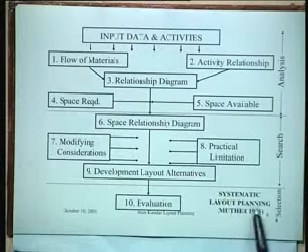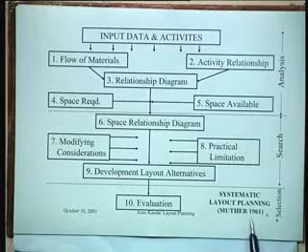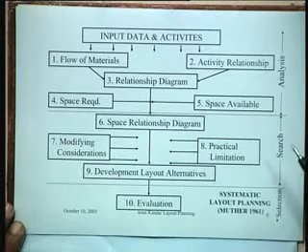Let us now look at the process of designing a process layout. Normally when you talk about layout planning, we are generally talking only about process layouts, because in a product layout, the layout is generally fixed by the sequence of operations, so there isn't much to design except to ensure that you have the space to lay out those machines. So there is a procedure which is called systematic layout planning, SLP. The SLP procedure of Muther, proposed way back in 1961, gave a general framework for how these process layouts are to be designed.